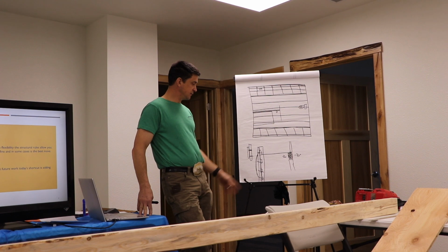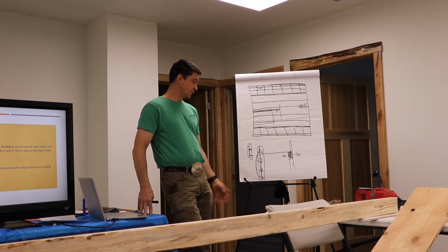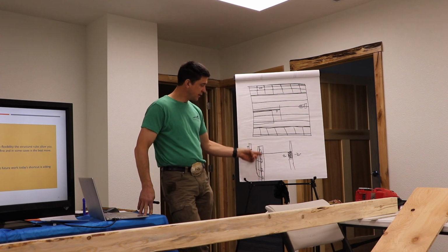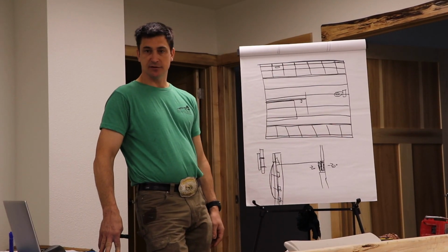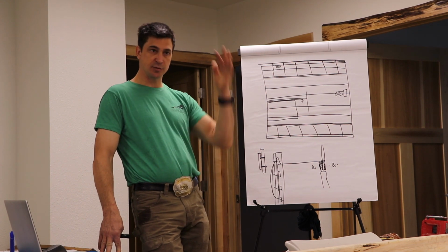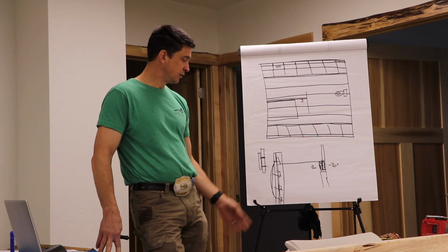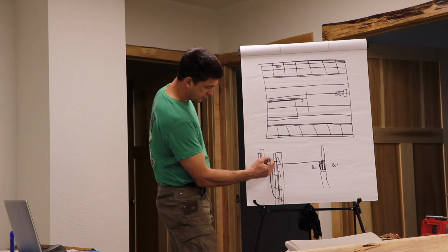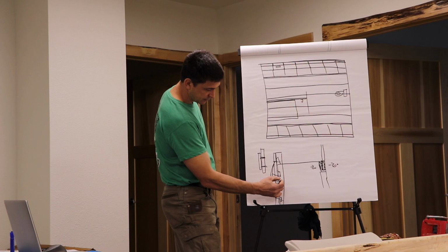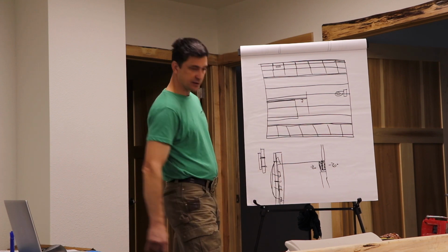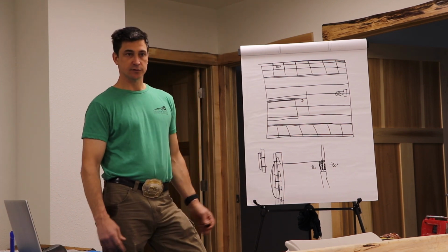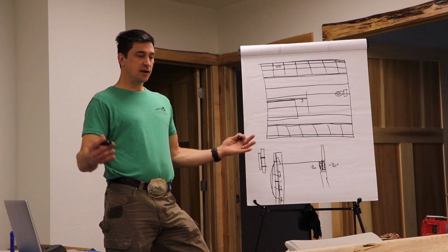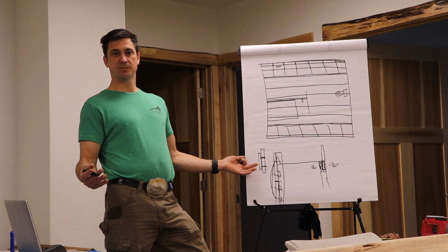The other thing is, if this is an outside wall or an inside wall, it doesn't really matter, but particularly if it's an outside wall, I get full cavity insulation. I don't have another piece of framing going all the way through the wall. It's really easy for my electrician to come and drill through one stud here to make that corner. So it's super easy for him to run his stuff. I can't think of any drawbacks for it.